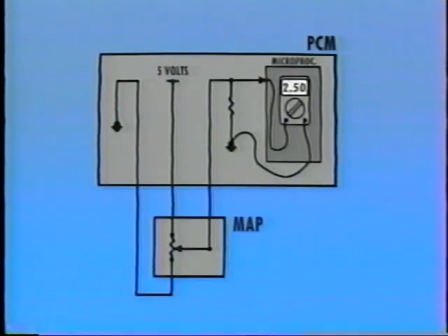On engines with forced induction, you could also raise manifold pressure above 1 atmosphere. In that case, the chip would flex slightly inward. As the chip flexes, its internal resistance changes. As the sensor's resistance changes, the PCM monitors the resulting changes in the voltage drop across its internal resistor.